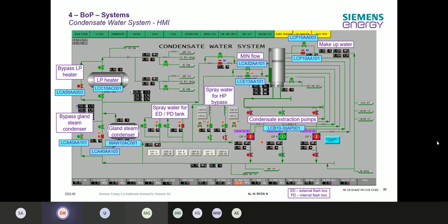Yeah, I mean, you saw the manual. I will check there again if I find something, but I think I also don't get all the manuals so far. So for me, I can just tell you, take a look for the minimum level from the hot well, protection for the pump. NPSH is the big word there, and if it's like this, then please check if it's somewhere in.